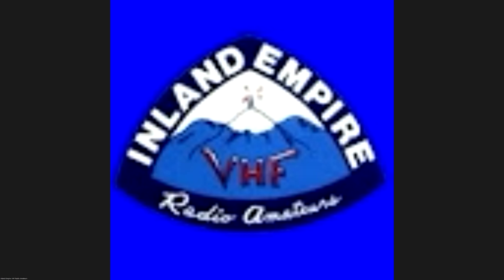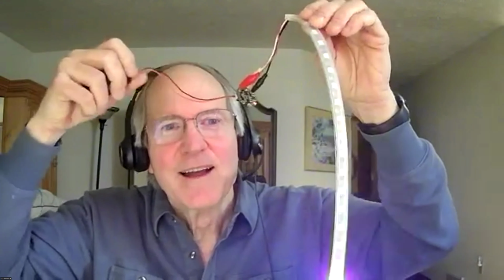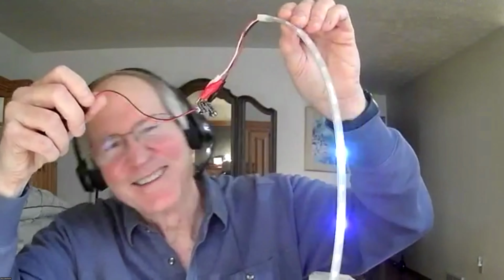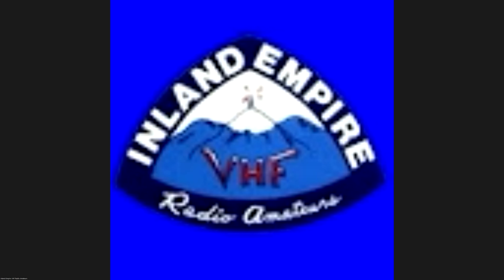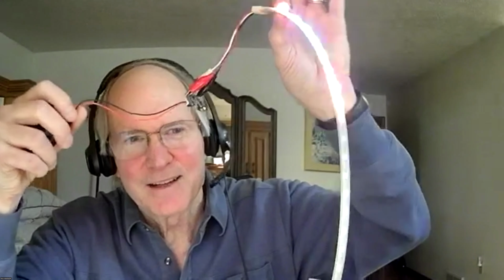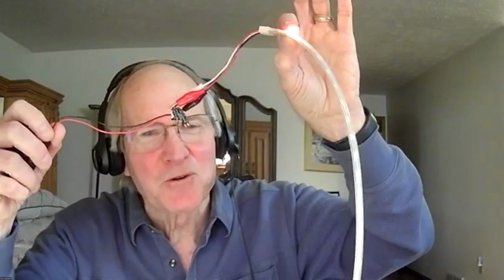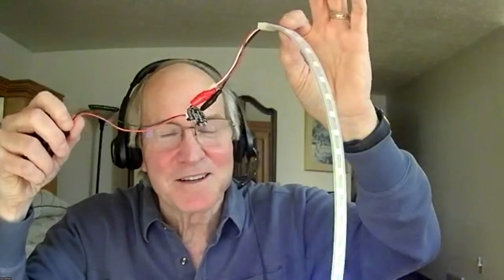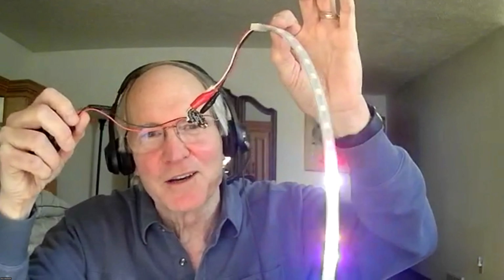Yeah. So this thing, that's 3 wires, but it's power, ground, and 1 serial wire. I actually got into this big time and wrote an FPGA program for my class I teach at SFCC. This thing is sending out enough ones and zeros, 24 bits per LED. It can update this 1,000 times a second on 1 wire. So a single 1 or 0 is about a microsecond and a half going out over this. And so, yeah, the update rate is still being paused here. It can go so fast streaming these things that they just blur into white.